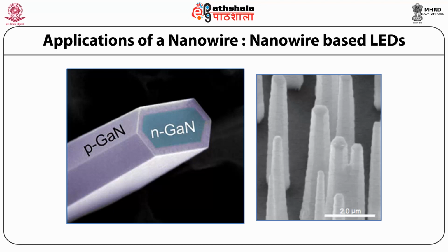Unfortunately, defects in the lattice limit light emission, introduce signal noise, and lead to early device failure. Among other advantages, flawless crystal produces more light. Now, for the first time, the electroluminescence from a single gallium nitride nanowire LED is sufficiently bright that we can measure its spectrum and track the spectrum with drive current to see evidence of heating.